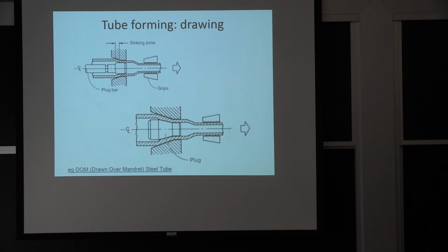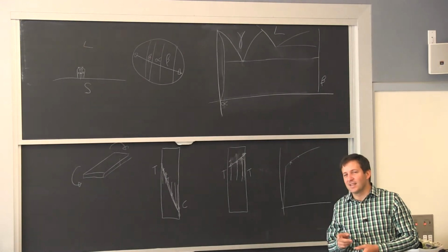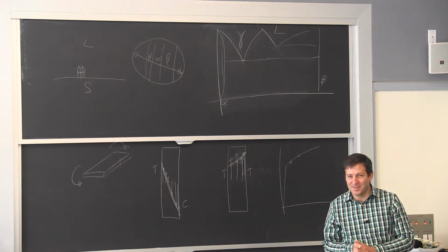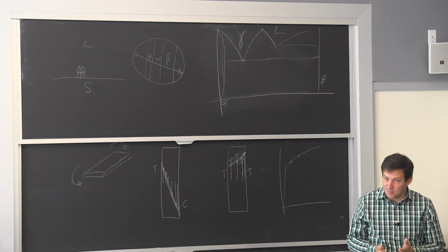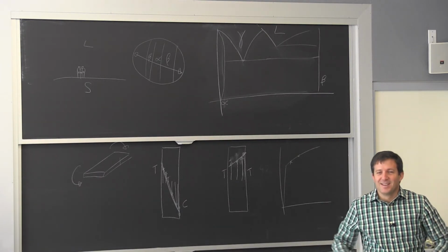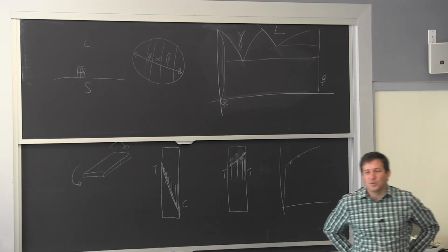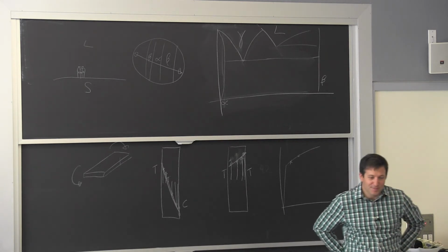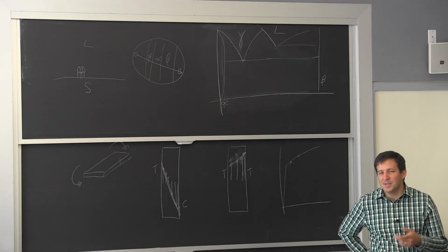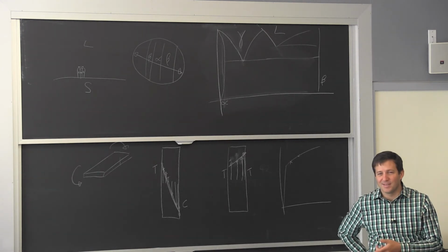And it's discussed in the ASTM standard. It says seamless. It doesn't say weld-free, so we have to give them that credit. They go into the detail that a seamless pipe essentially, well, there's also the difference between seamless and seam-free, okay?